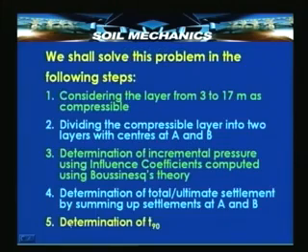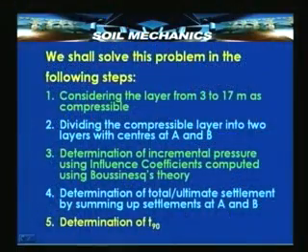We shall solve this problem sequentially. Now, what are the typical steps which are involved? Number 1 is identifying the compressible layer, which I have just now mentioned. 3 meters to 17 meters, 14 meters, is the thickness of the compressible layer. Then this compressible layer is divided into parts.